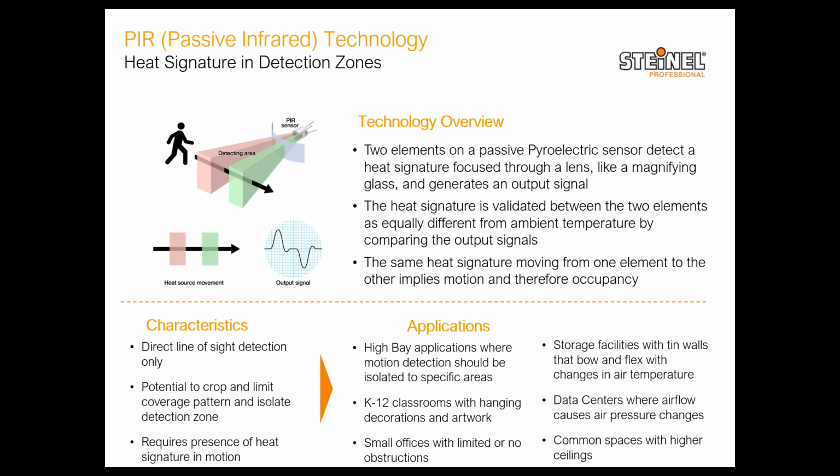And our sensor with a high definition lens and high definition pyro elements, and not one, but 4 pyro elements, will give you 4800 switching zones. So a good PIR, a high definition, high quality PIR with a lot of switching zones, is the perfect solution for many applications that you would have to dismiss if you have a low quality, low resolution PIR sensor.